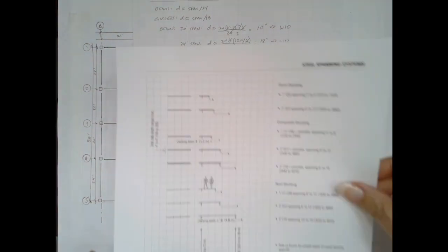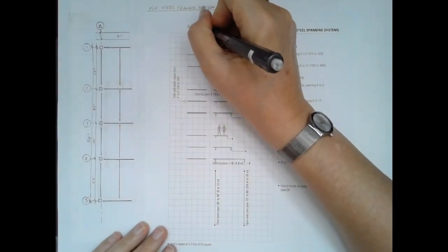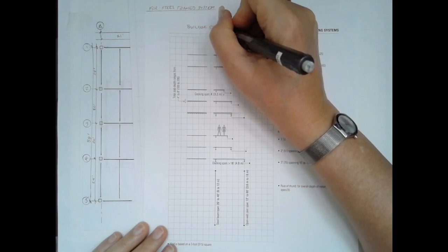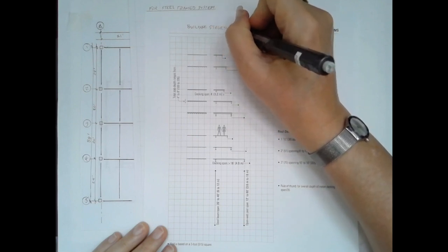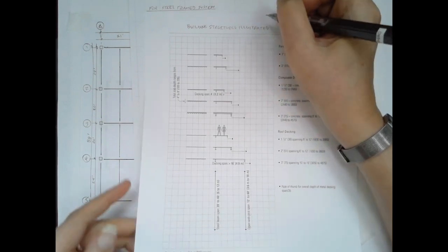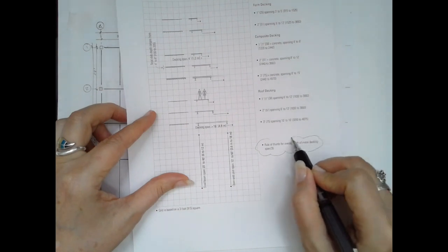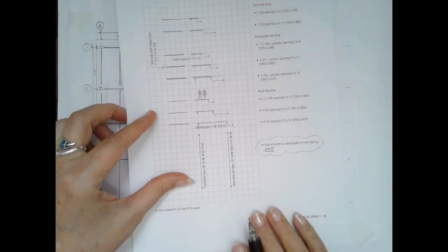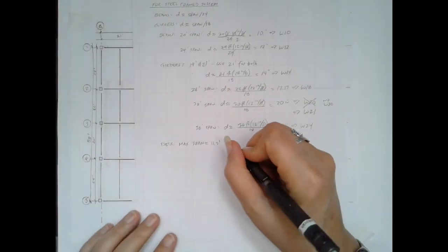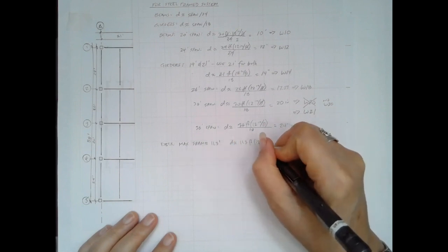Now the ratio, I'm using this from the Building Structures Illustrated book, and this is on page 123 out of that book, and that says a span ratio of span over 35 for the approximate depth.